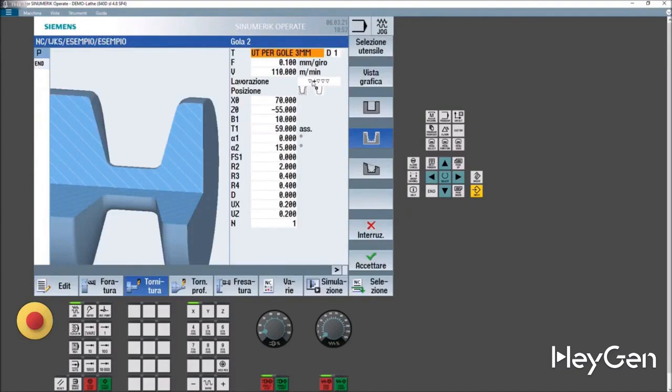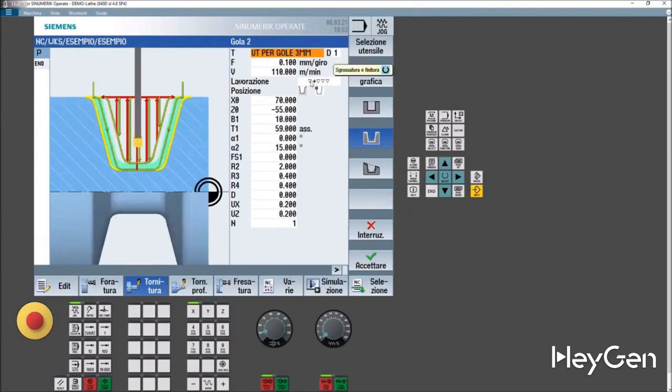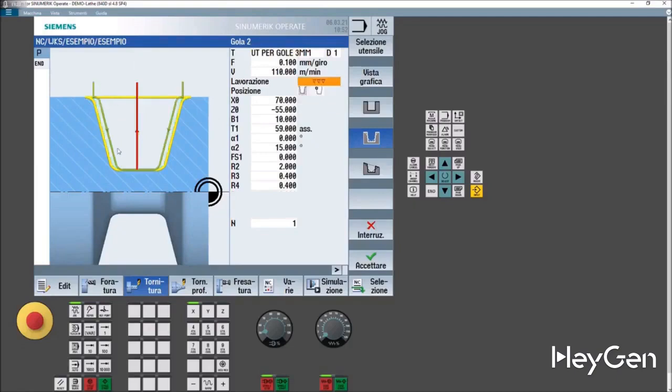To work on our groove, our processing, you can see that the groove is already inserted. It's done. More roughing though. You can also just rough it out, just finish it. So it enters, lifts, moves, and goes back in. Or you can rough it out and finish it normally. With the groove tools, you rough and finish X0. So you see that it measures the left point. Do you want to work with the right point? Just change this soft key.